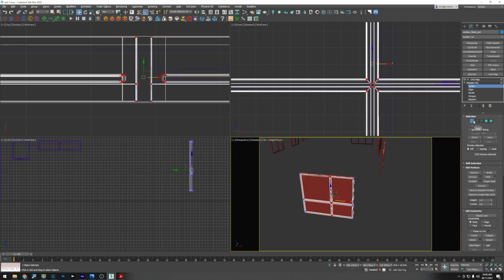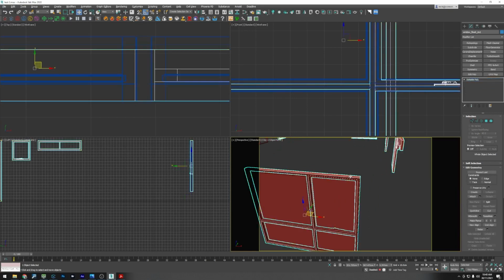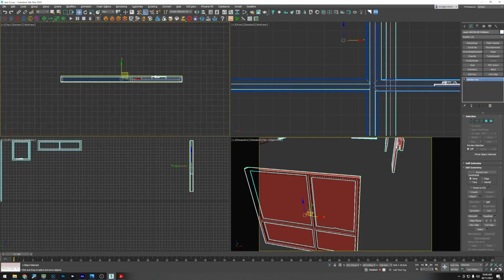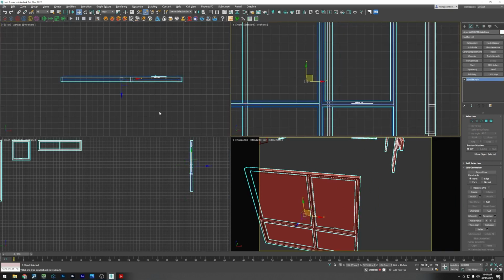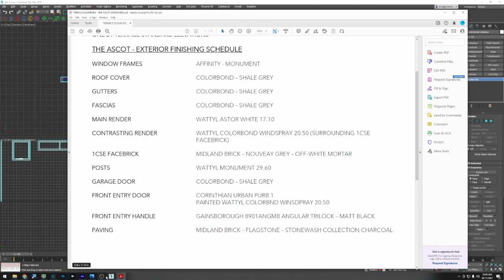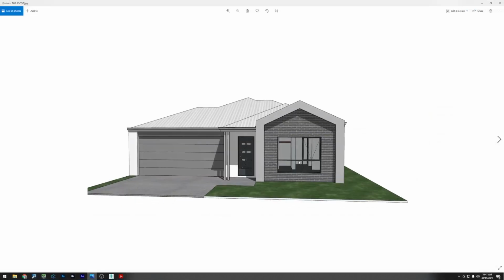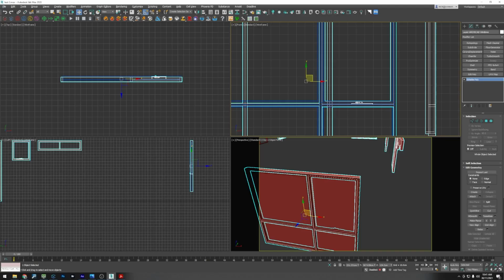And that's that. Now, as you can see, the original window frame here has actually got an awning window in one of them, and you can tell that when you look at the elevations and plans. You can see they've usually got like a dotted line, which signifies that that window can be opened, and you can see that there's like a frame within the frame. So we actually need to convert our window a little bit.